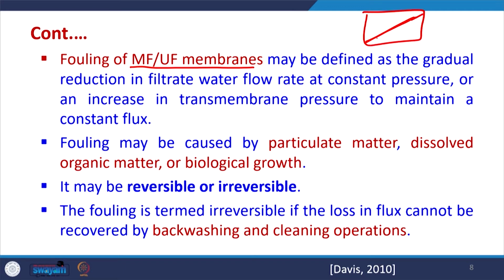If the same pressure difference is applied across this membrane, because a new type of cake resistance is coming into the picture, the treated water coming out will decrease with time if constant pressure is applied. Now, if we want to retain the same amount of permeate, we have to gradually increase the transmembrane pressure with time. This has to be taken care of if the required permeate has to be maintained at a certain level.